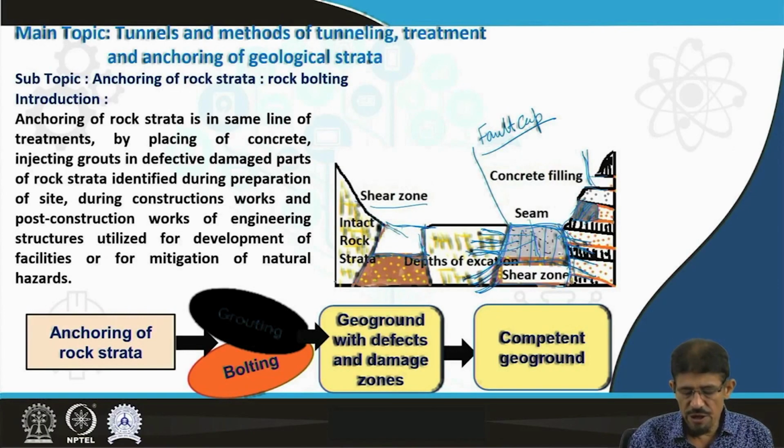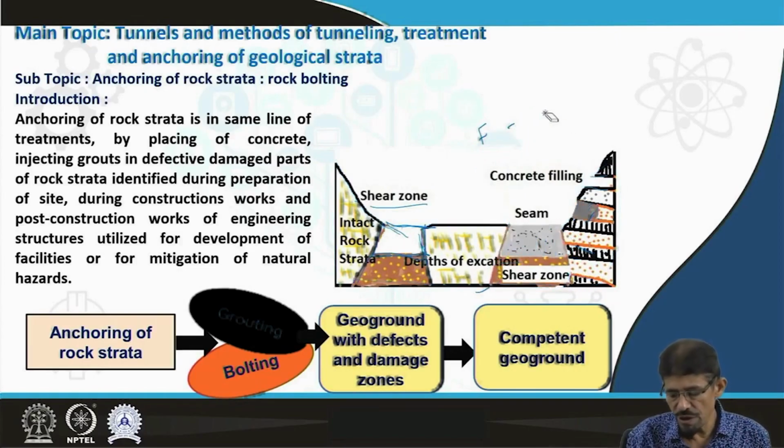As far as treatment, we are going to insert either grout, cement grout, chemical grout, or simply concrete, or mortar, or other clay materials, etc., to enhance the ultimate strength of rock strata for future engineering application.